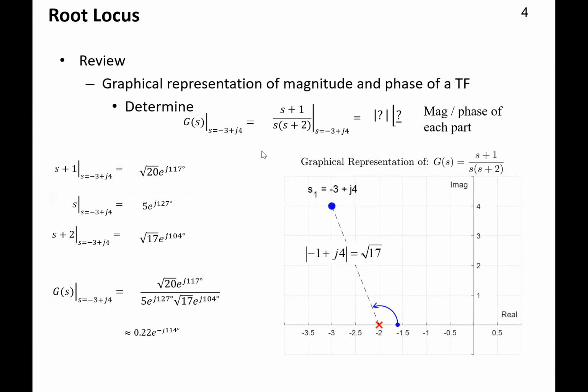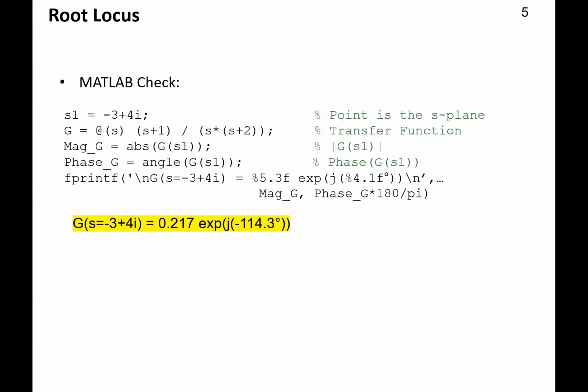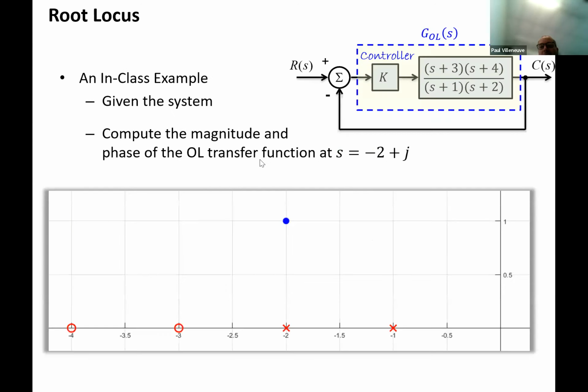I have it in rectangular form if that works. I need it in polar form because it'll be better to see magnitudes and angles looking at this plot here. I can do it right now, I have my MATLAB set up right next to me. All you have to do is abs and angle times 180 over pi. That should give you those numbers.